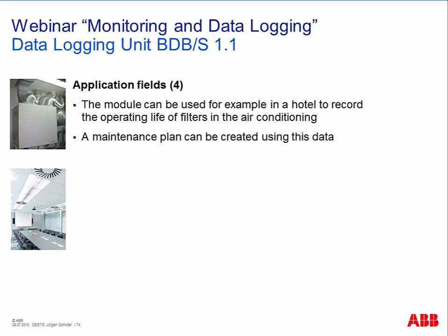Or, for example, in ventilation systems or in fans and blowers, we have the information depending on the operating hours that we have, for example, to replace the filters or to clean the filters when we reach our limit.